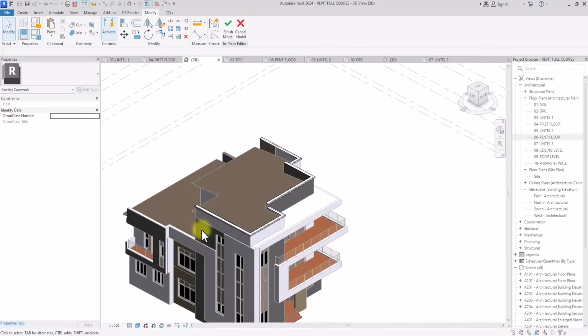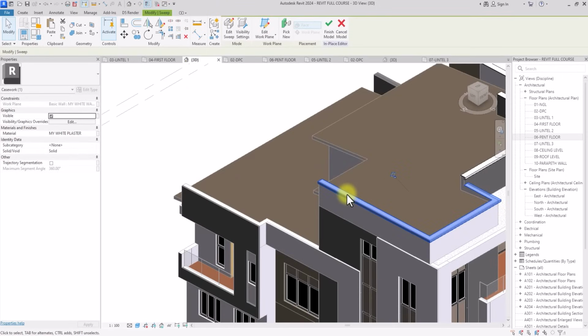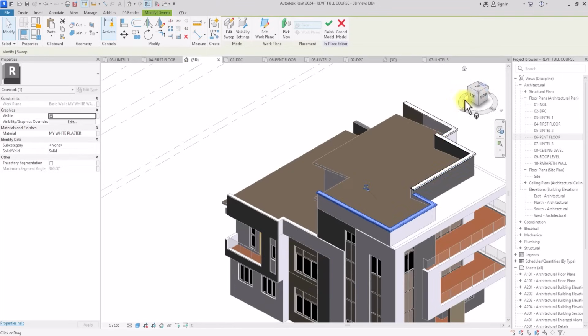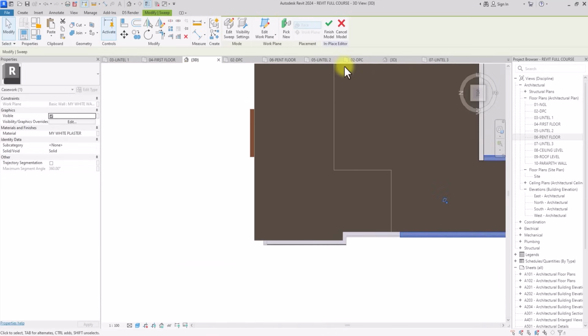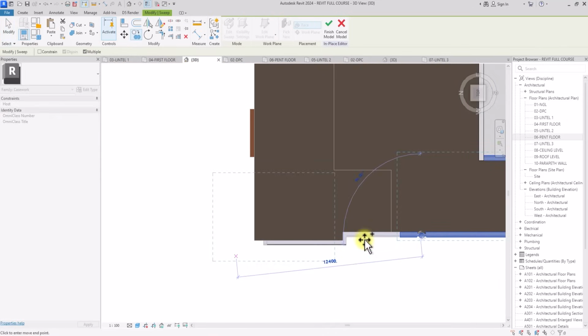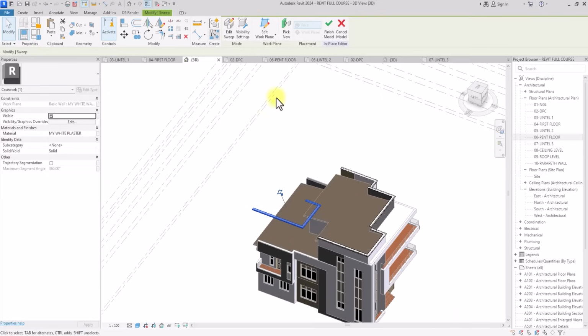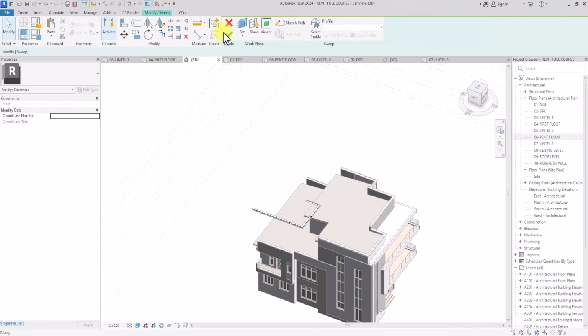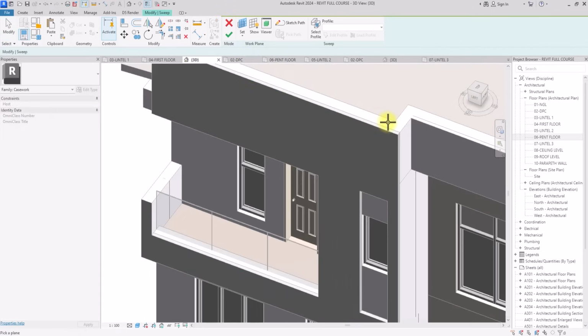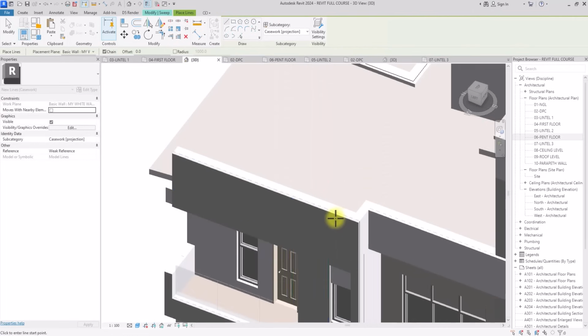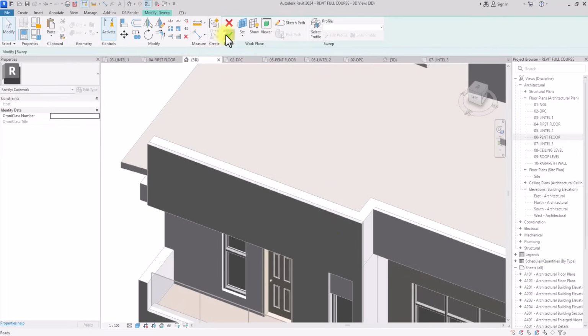Or let's just do it. We're going to do a copying, but it will be a different profile, because it won't be appropriate that a parapet wall doesn't have a copy. So we're going to copy this. So what we're going to do is we're going to, of course, edit sweep. We're going to click on set work plane, pick a plane, and we're going to pick on top of this lower parapet wall. We're going to set it. Then we're going to click finish.